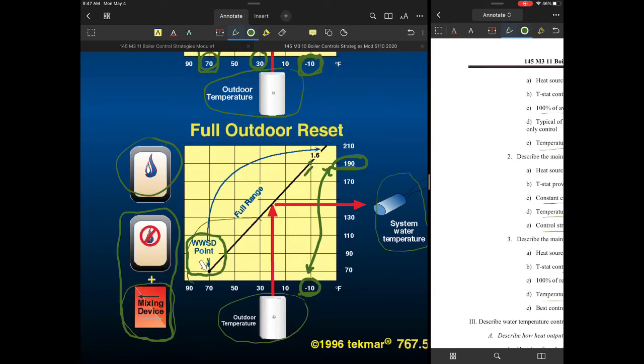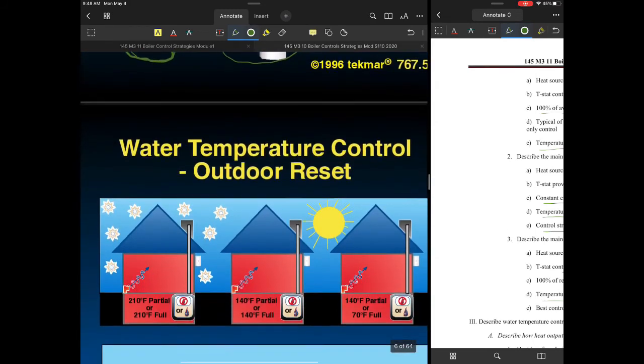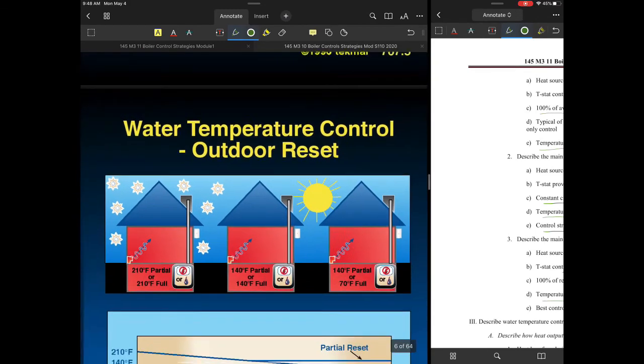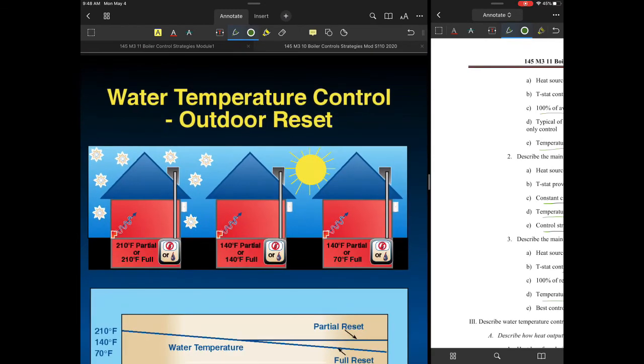So in this example, what we're doing is we're saying we're going to take this area that we lost control of, and we said we're not going to go lower than that for the boiler. And what it allows us to do is say, okay, we're going to take that area and let you continually go down. So that means now at 50, I'll let you go to 100 degrees. And at 60, we might say, well, we'll go down to 80. You have to identify all those points.